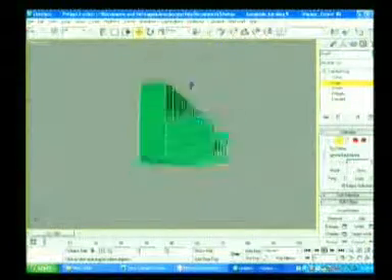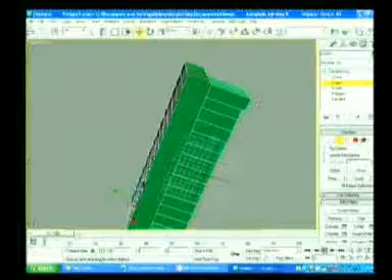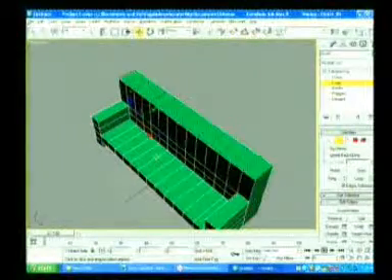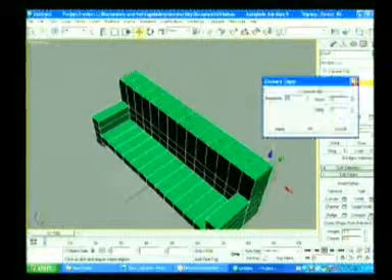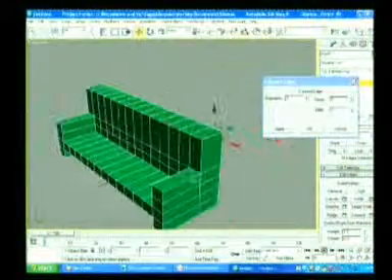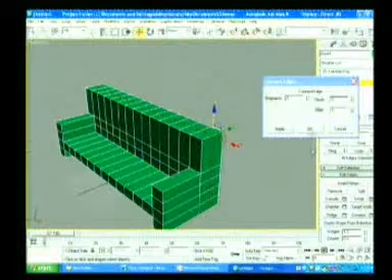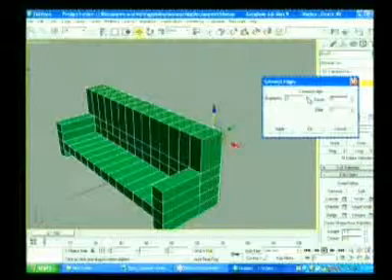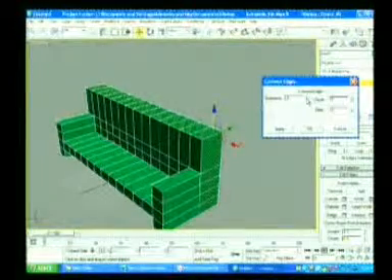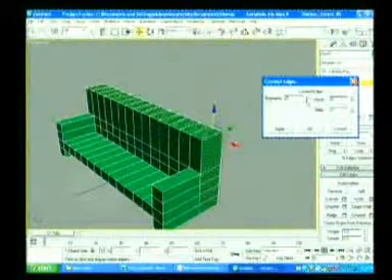According to ring, all the edges are going to be selected, then press the connect command. The segment form here, if you want to put 2 edges or 4 edges, 5 edges, increase the segments from here.